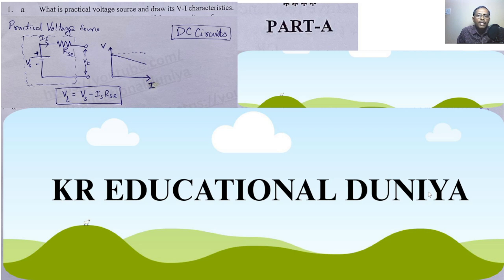Coming to the VI characteristics, in the x-axis we draw current and in the y-axis we draw voltage V. As the current increases gradually along the x-axis, the voltage line slowly decreases, as it is dependent on the current. This is the diagram of the characteristics. Also Vt, the output terminal voltage, equals the source voltage minus the drop. What is the drop? Is into Rsc.